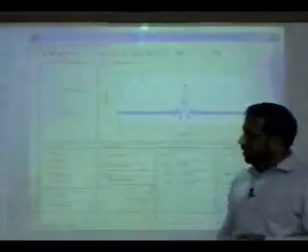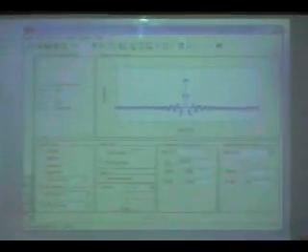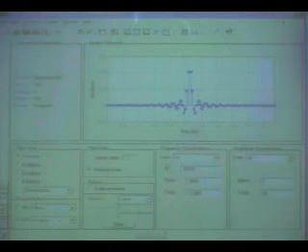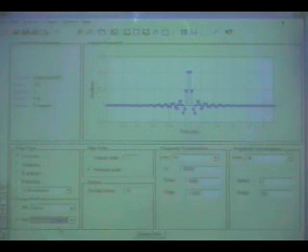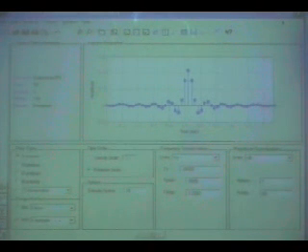So if you look at it, Kaiser says, what is the order? 101. And if you say equiripple, equiripple is the Parks-McClellan design, the same filter can be done in 50 coefficients. You can just see, Kaiser used to be the best, because Kaiser says, just tell me deltas and A's and I'll give you the best window.